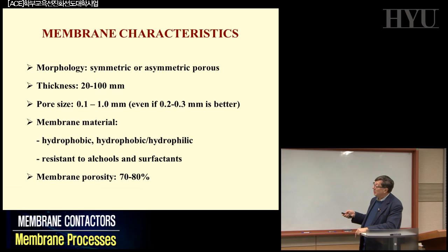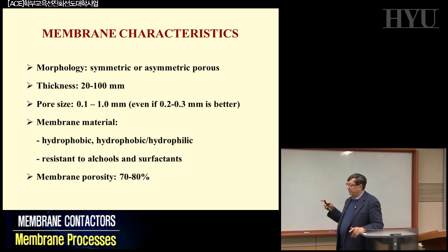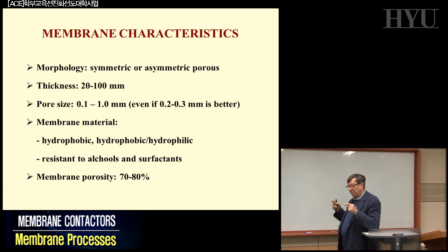This membrane can be symmetric or asymmetric. We don't have any big problem in this case, also because, as I was mentioning, traditional fouling is less severe. You can have situations of big fouling if you are working in nanofiltration or ultrafiltration, because you have convective flux to the membrane surface.